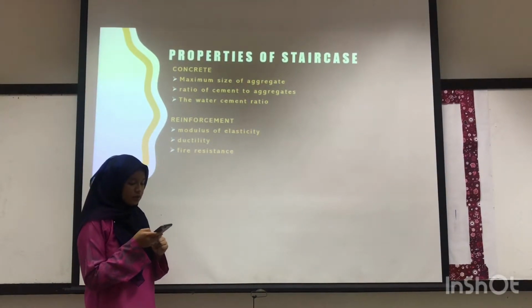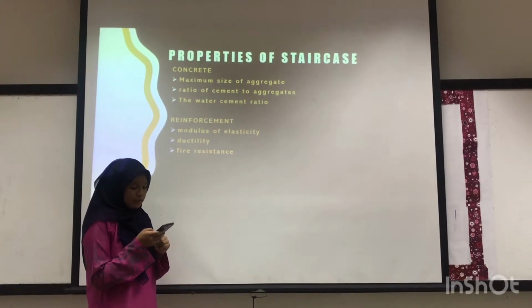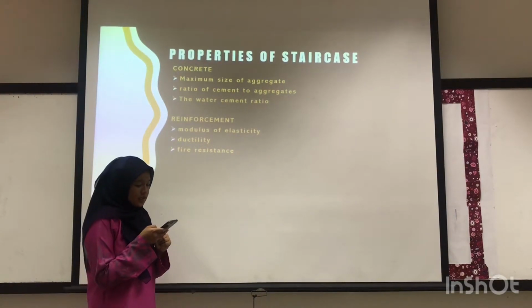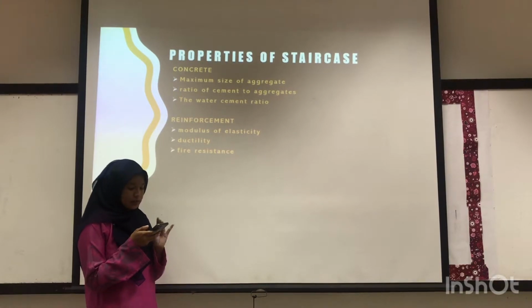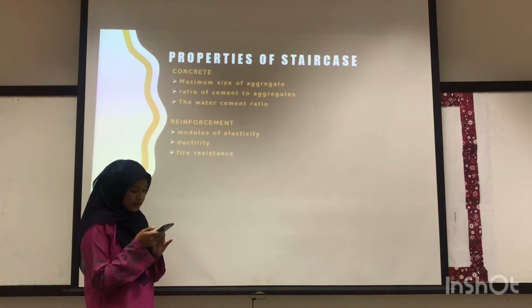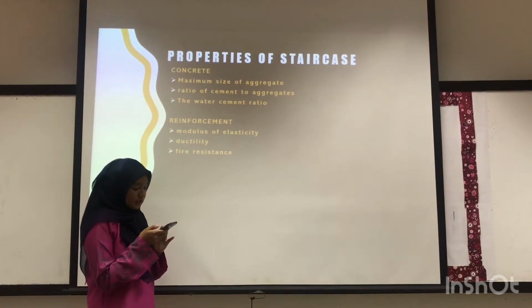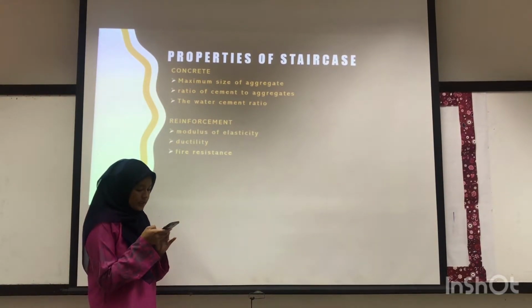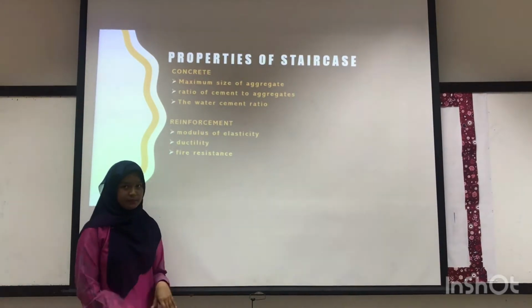Too much water will result in segregation of cement and aggregate component for the cement paste. A mix with too much water will experience more shrinkage as excess water leaks, resulting in internal cracks and visible fractures, particularly around inside corners, which again will reduce the final strength.